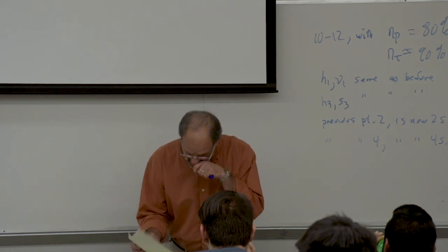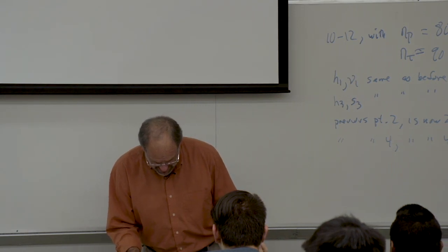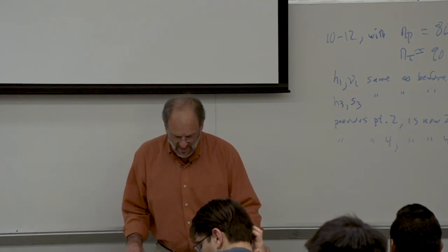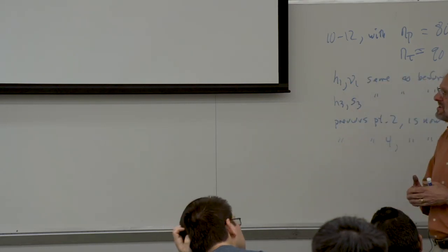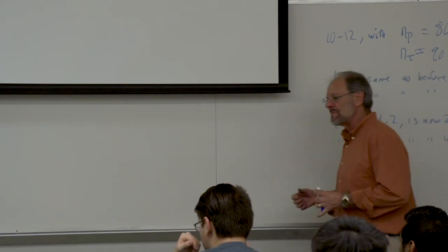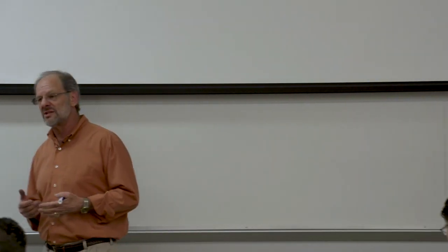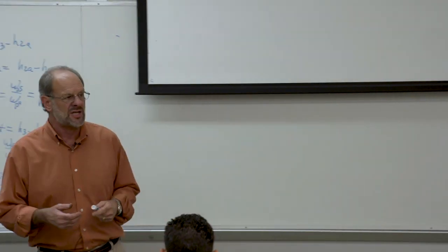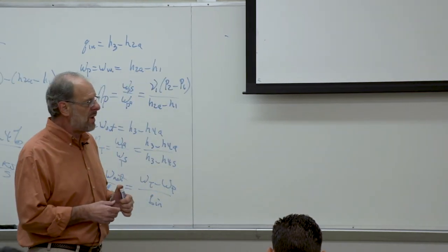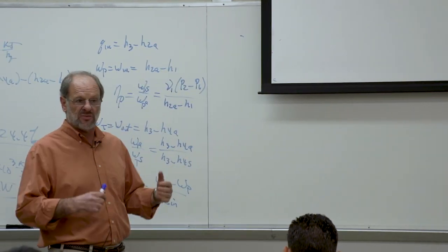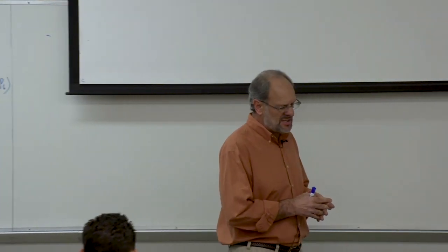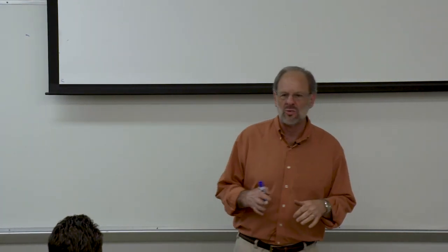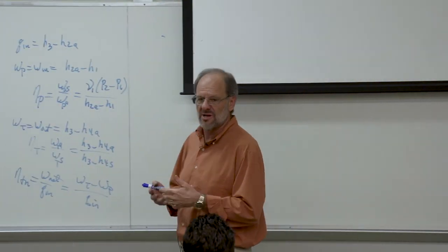So one thing that I should note is that there are ways that we can improve the thermodynamic efficiency of a Rankine cycle. And some of these ways are similar to what we would have used in the Brayton cycle to improve its overall thermodynamic efficiency. One thing that could be done is regeneration. But regeneration is a little more complicated with regards to a steam cycle than it is for a gas power cycle.